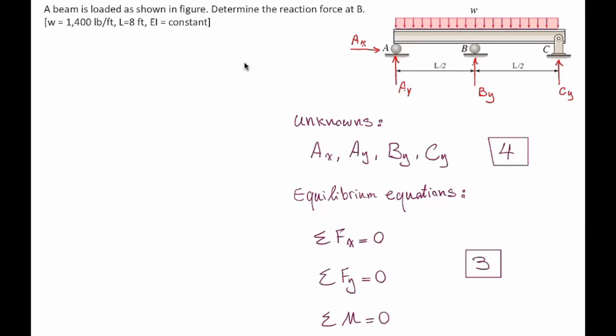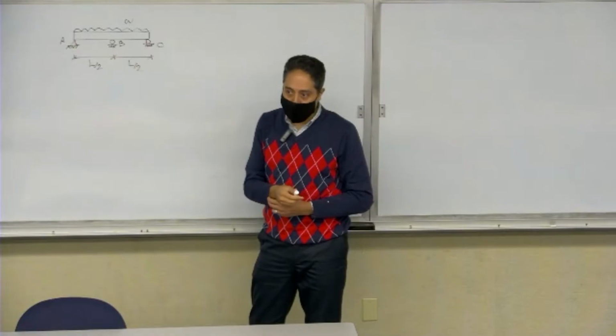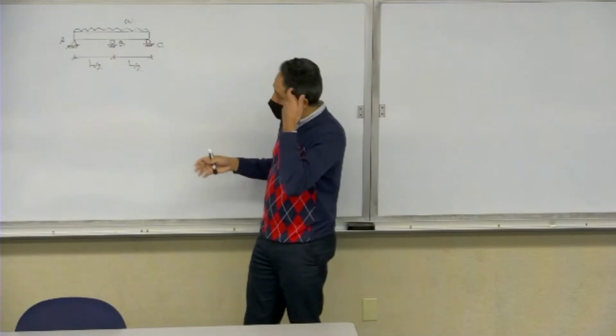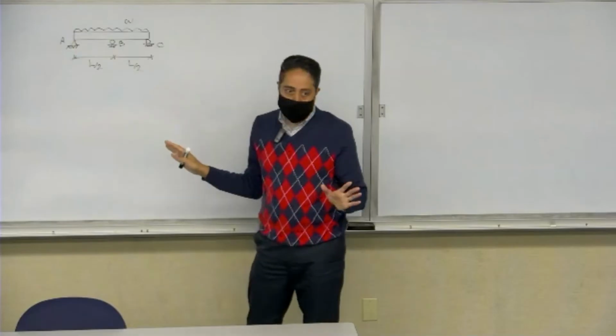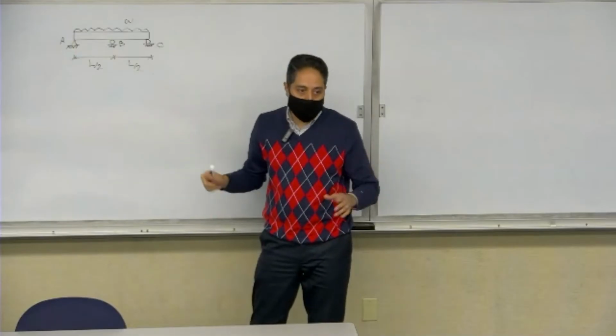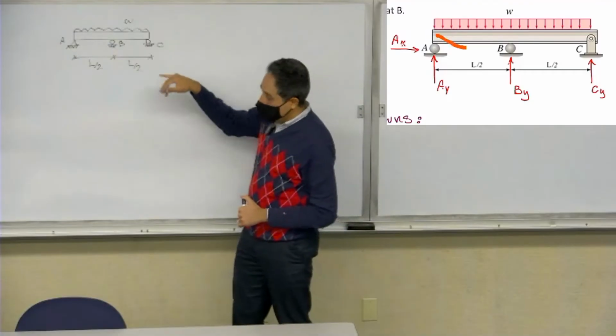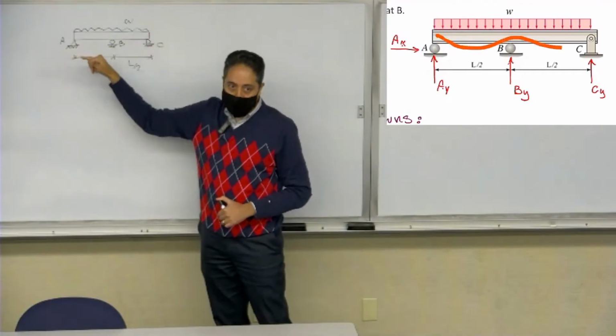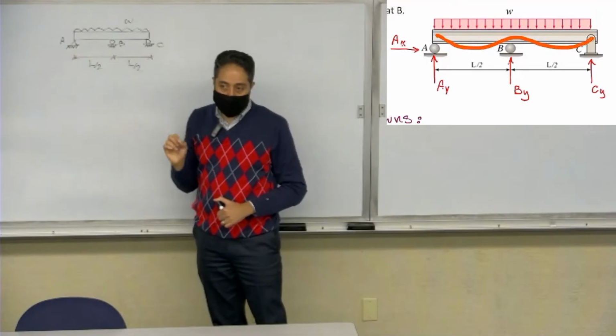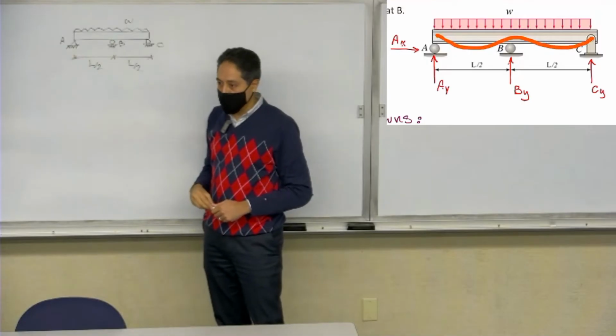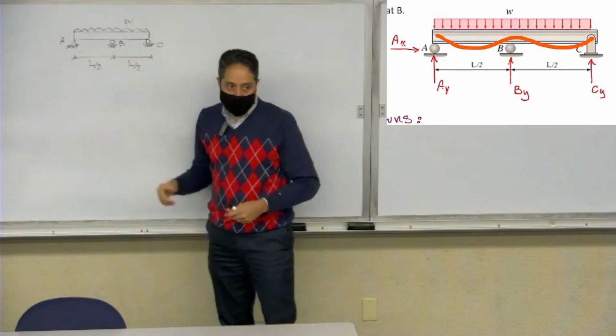This problem is called indeterminate, statically indeterminate. So if it was statics, we couldn't get the reaction forces at all. There is no way for us to solve this problem. But with mechanics of materials, knowing how much the element is deforming, we can get extra equations from the compatibility of deformation and solve this problem. This is what we want to do.